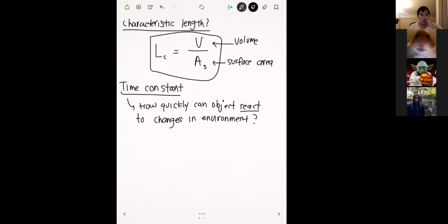Okay. And to do this, we're going to look at basically the rate, right? We looked at this a little bit at the very beginning of lecture today, where we computed how long it would take the ice cube to go from one temperature to another. And if you remember, the thing that primarily determined this was the coefficient in the exponent. So if we define our time constant, we'll call this tau_t, to be rho V c over h A.